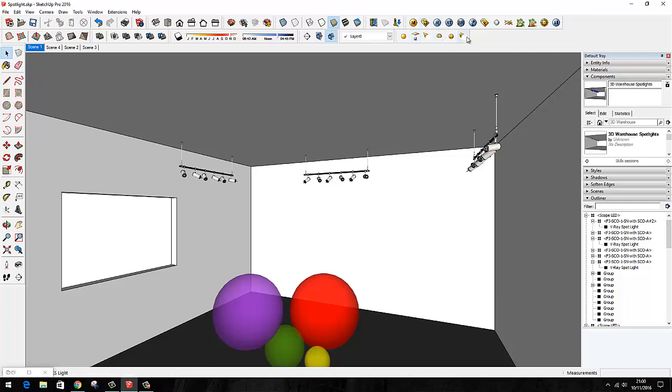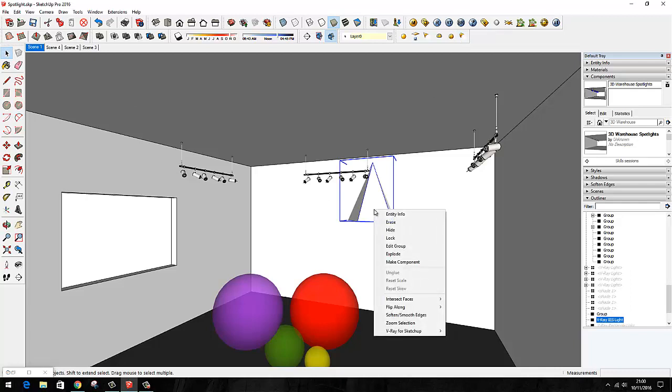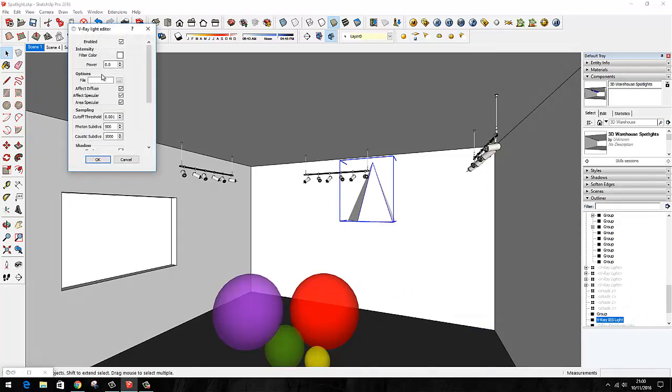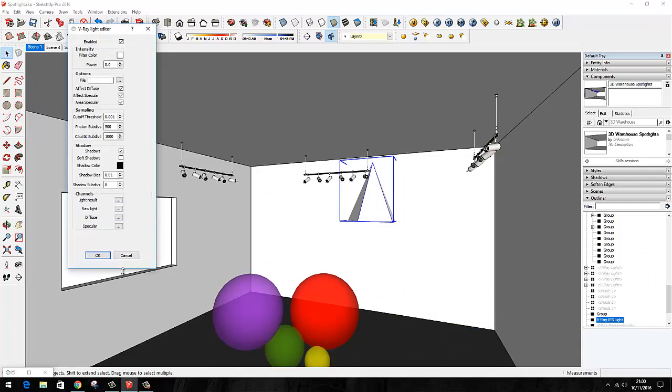Next we'll be looking at this type. Now this is an IES light, and if we pop an IES light in, it looks different. And then edit light. Let's just drag this all the way down. A lot of the settings are the same, but there's this option here for an IES light file. That's going to give you a very unique flooding from the light. If I just pause this one more time, I'll see if I can dig some up so you can see the sorts of patterns that you can get from IES lights.